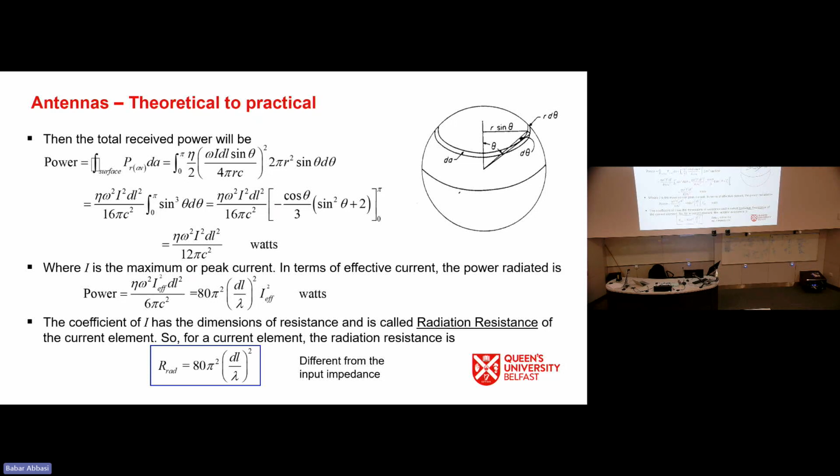But if I want to cover a sector, say from this point till the HB building, and I want to build an antenna on top of the HB building just to cover this area, then I need to know how much sector it can cover and what kind of power I need to push into my base station antenna so that I will receive a particular power in that given sector, so that your mobile phone antenna can actually receive something and you get your full bars of signal. That can be manifested easily using this kind of power equation.